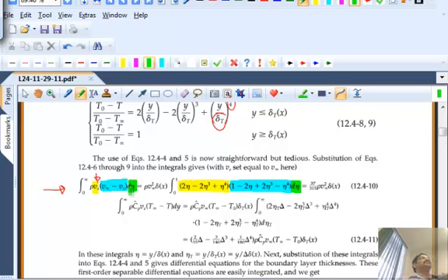It's a fairly easy integration to do, even from an exam point of view, because all you need to do is take integral of x to the power n, for example. So here, eta to the power 8 you might have when you take these two terms, and then put the limit between 0 and 1. The limit is between 0 and 1. So you'll get this expression, 37 over 315 rho V infinity square delta x. That's the right hand side of that equation.